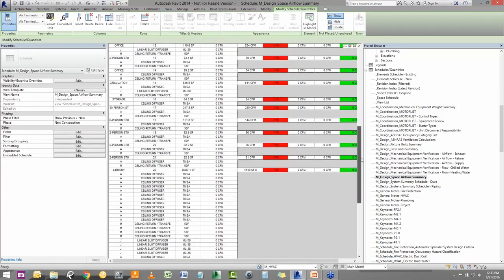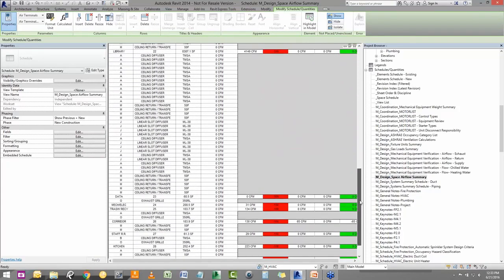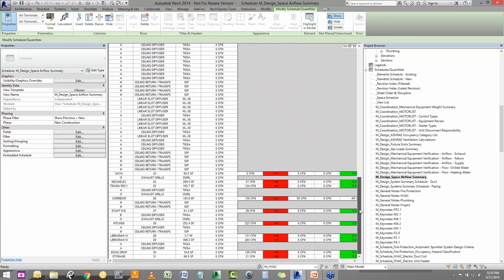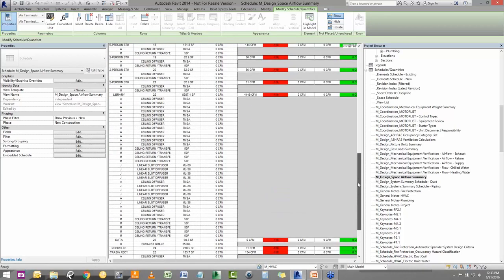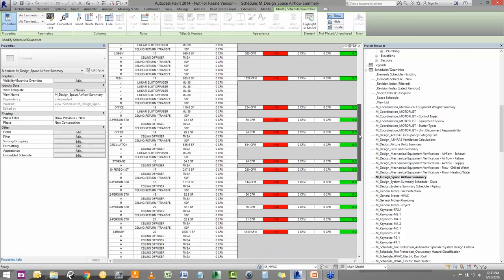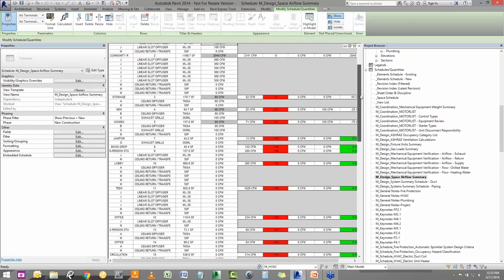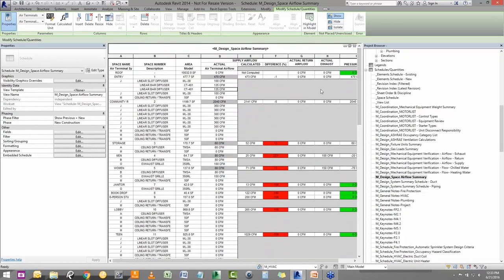not having to go from view to view to view to go ahead and do any flow rate typing for each diffuser, because we know that that leads to some issues. You always forget one or you miss one or something happens. This way you're able to do it from the schedule, automatically compare that right away to your calculated CFM, and go ahead and basically complete your supply air data entry.